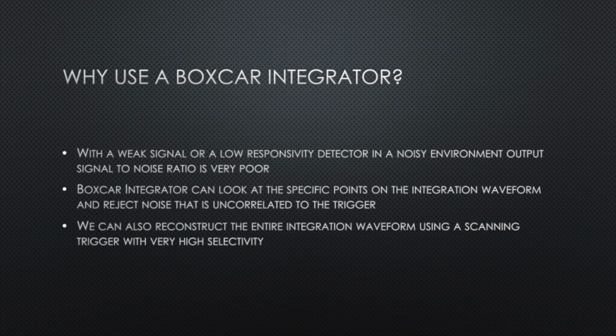In the last video I showed an LED source follower type detector, and in that video you could see a lot of noise coming from various environmental sources, mostly 60 Hertz noise, either electrically being picked up or optically being coupled into the LED through room lighting. So anyway, if you use a boxcar integrator, it's possible to get rid of some of these noise sources and not be sensitive to them.